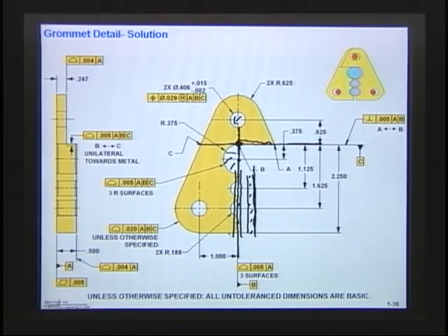For example, this outside, see, within profile within 20. How many points are they going to check? Probably if it's a lot of tolerance, they're probably going to check less. If it's a tighter tolerance, they're going to check more. It depends on the process, how the part was made. Is this the first part you're checking, or the 100th part you're making? What's the tolerance? Who made the part? What do you know about the part? But one way they could do it would be they have their origin.